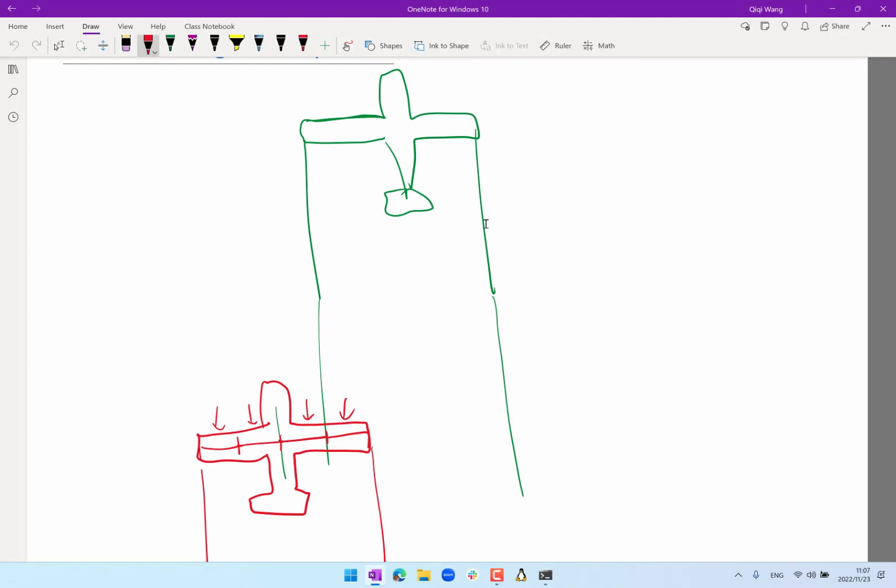So if you have four vortices, right, one coming from the tip of each side of each aircraft, we can split up each wing into multiple segments and look at what the downwash is at the center of that element. For example, we can split the front aircraft into 4 segments, split the back aircraft also into 4 segments, and use the formulas to compute how much downwash is on each segment. The downwash combined with the speed of the free stream allows you to calculate how much the lift vector is tilted backwards. And the backwards component of the lift vector is what makes induced drag.